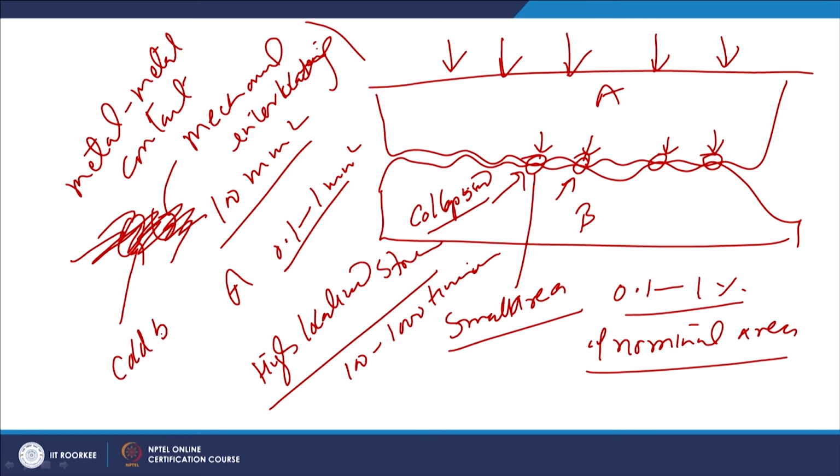cold bonding. So, the components which are brought together in direct metal to metal contact will have some kind of bonds between them. Since there is no external heat, still the joint is being formed under the external stress conditions. So, such a bond is termed as a cold bond.